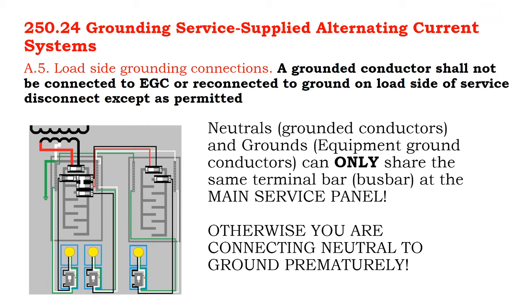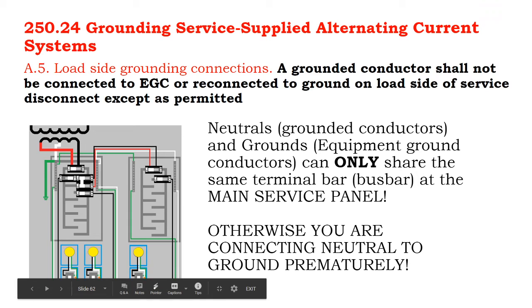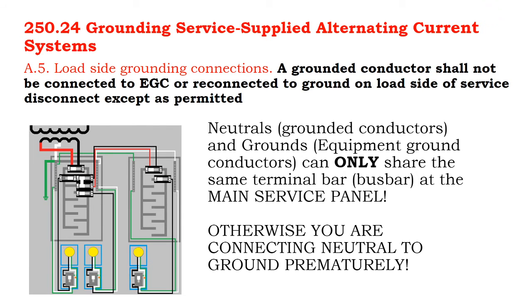If your solar array is tied in as a load side connection and not on a standalone dedicated panel that taps into the utility conductors, but if your solar array comes into the bottom side of the bus bar on a load panel, you might read something in code that says make sure that the neutral is connected to ground. Don't doubly connect it to ground. Make sure it's only connected to ground at one point, like it is on an existing facility.